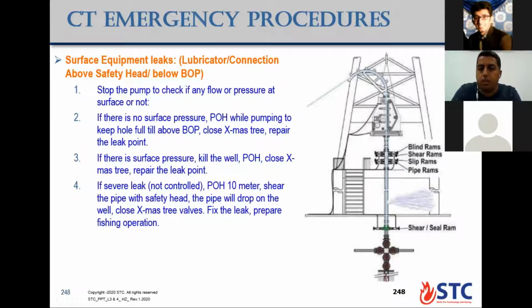Yes, you can bullhead from the annulus between the coiled tubing and the production string. Actually, the leak is also from the coiled tubing annulus, as the lubricator is leaking. Or you can pump from the coiled tubing. If you pump from the coiled tubing, the pressure may come down inside the wellbore, so it will be better than having high surface pressure at that moment. You try to minimize or reduce the surface pressure to keep the pulling out safe if you are deep inside the wellbore.